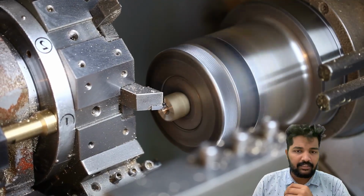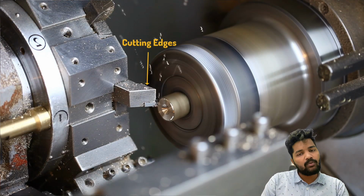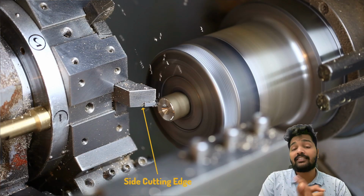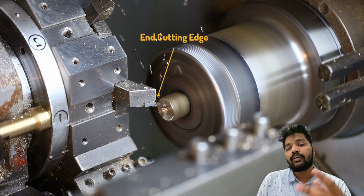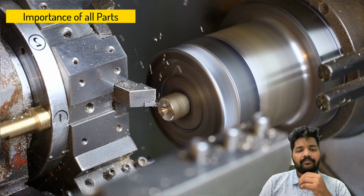Lastly, we have the cutting edges. Now the cutting edge is the sharp edge on the face of the tool responsible for the material removal from the workpiece. It consists of two primary edges. One is the side cutting edge, that is also called the major cutting edge. Second is the end cutting edge, that is also referred to as the minor cutting edge. Now both of these cutting edges contribute to the overall cutting performance of the tool.